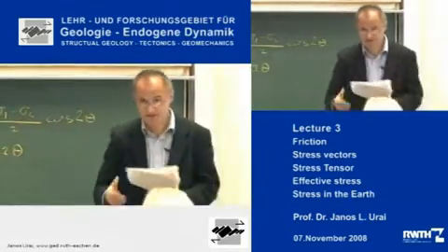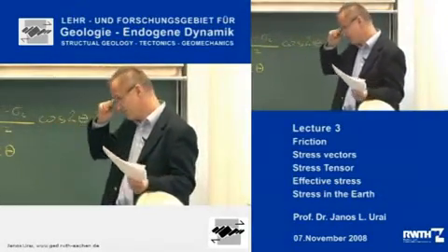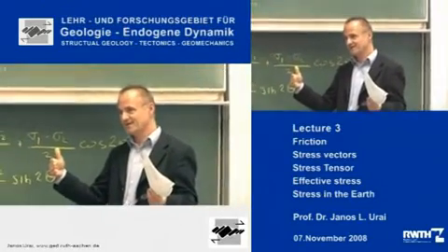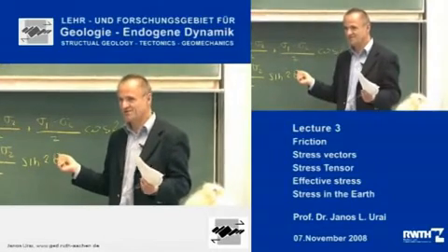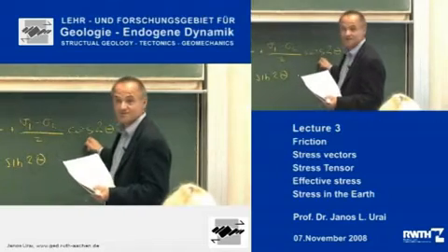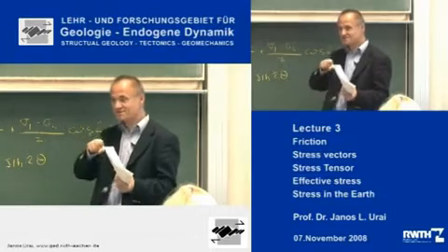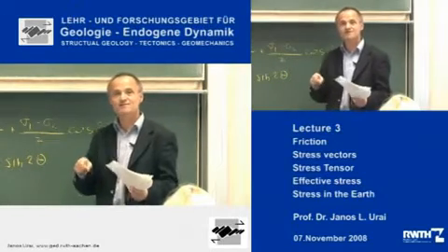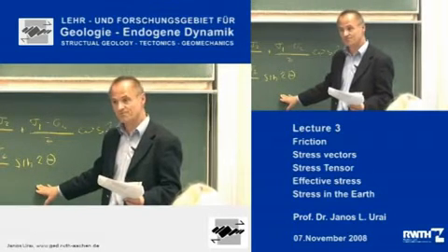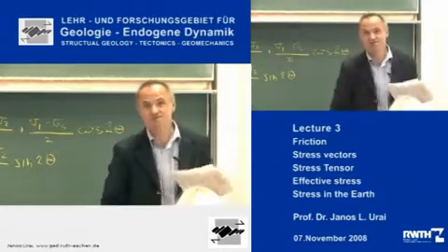And this is a very interesting way to express the normal and the shear stresses on this plane, because maybe you remember that in quantitative geology course last year, we made a plot of the sine of an angle against the cosine of the angle. If you plot the sine of an angle against the cosine of an angle, what you get is a circle. So this here is the equation of the circle. And this circle is called the Mohr circle. It was invented by a German engineer, Otto Mohr.